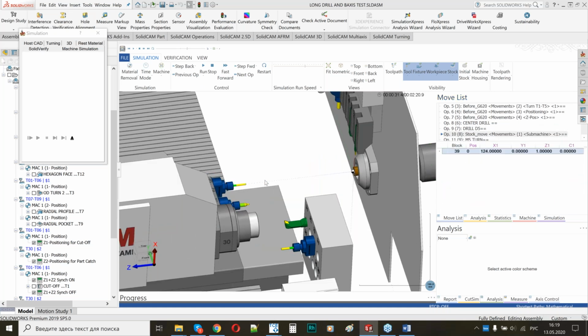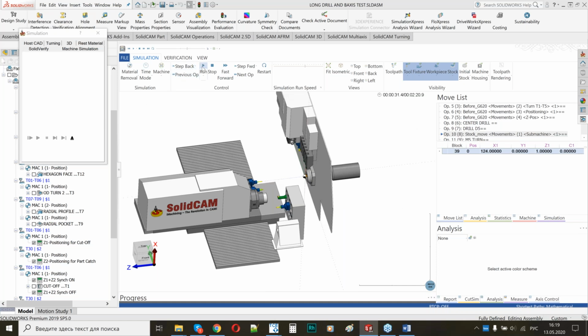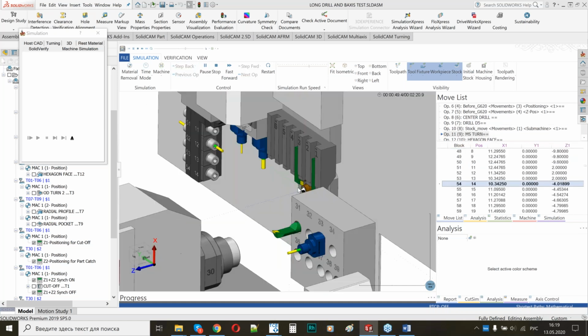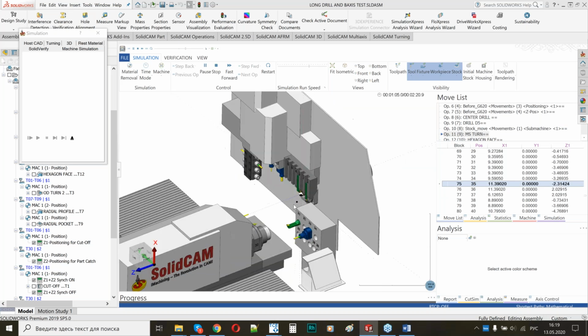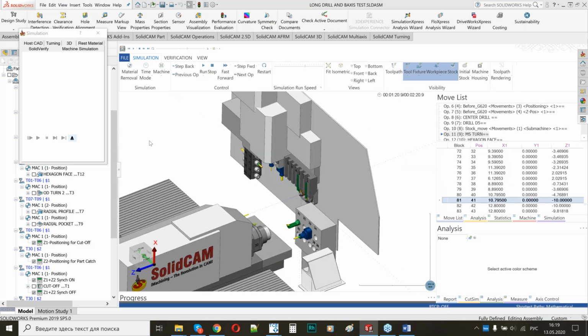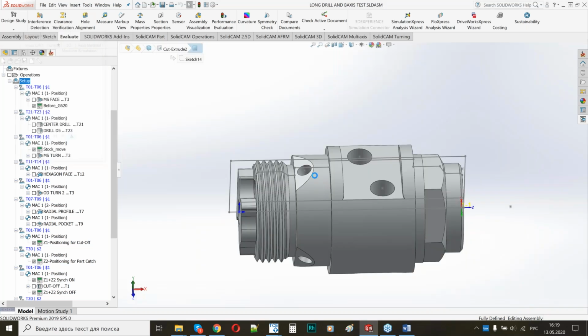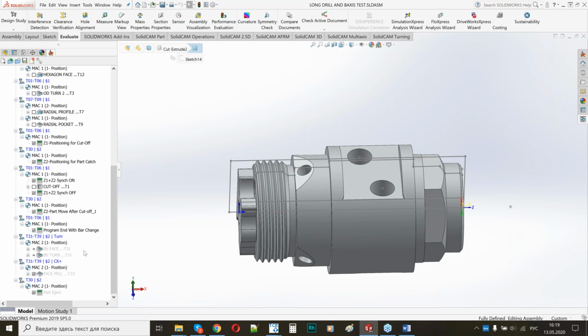This is my safety retract. And now the other operations, which you saw previously. I will stop it. So very easy, but you should know what the requirements of the machine are for such type of operations, of course. The next operation I'm gonna add is inclined milling.